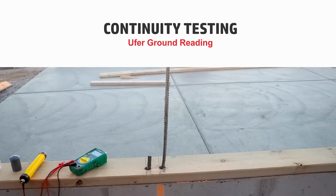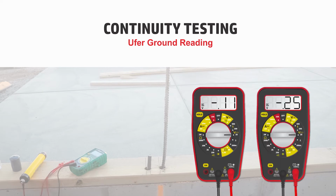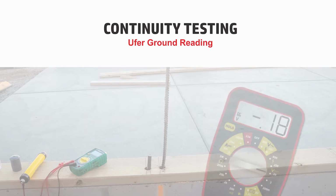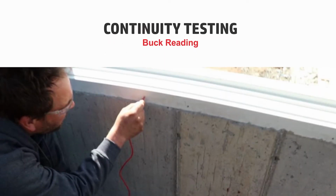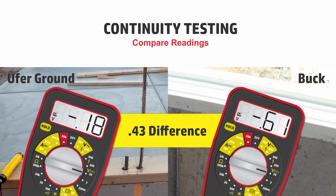A typical UFR ground reading will be between -0.11 and -0.25. For the home shown in this video, the UFR ground read -0.18. This is normal. Test the window buck. Scratch through the finish with the red lead and take a reading of the buck. On this home, the continuity test on the buck read -0.61, a 0.43 volt spread.